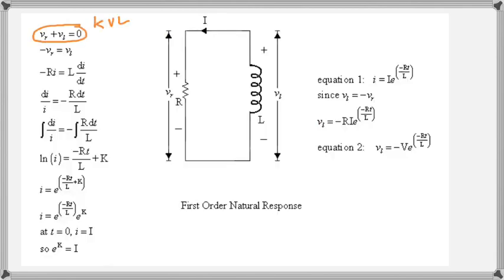Now, we are doing the same analysis we did before. We have a fully loaded coil. That coil has a big magnetic field around it, which is now about to collapse back into the coil to create the electricity. You notice there's no voltage source or anything inside this circuit. It's a fully charged coil which is about to discharge through the resistor as its magnetic field collapses.